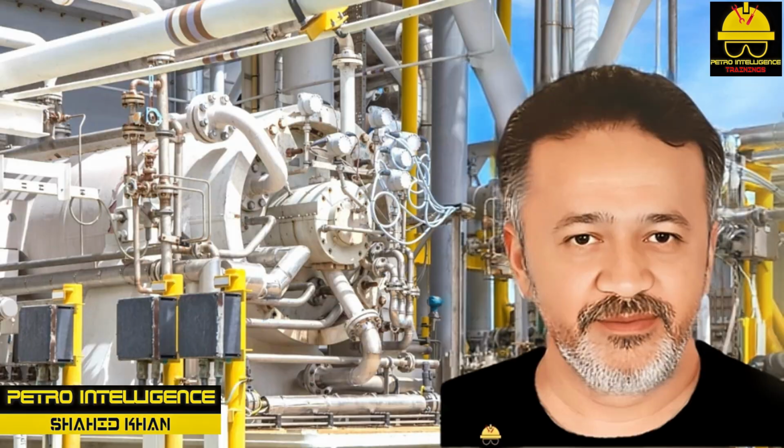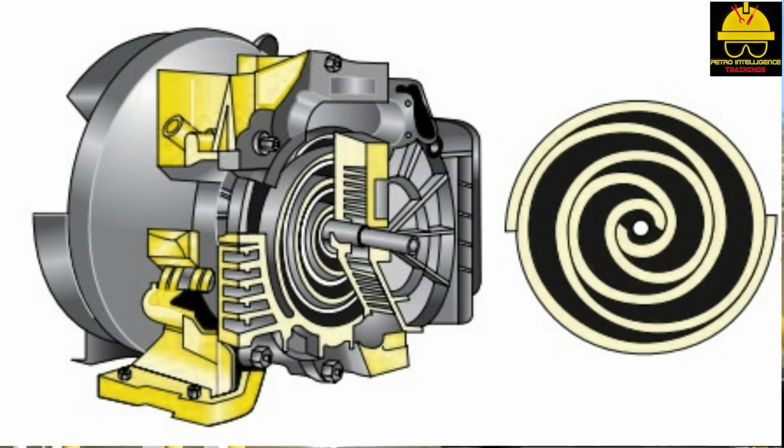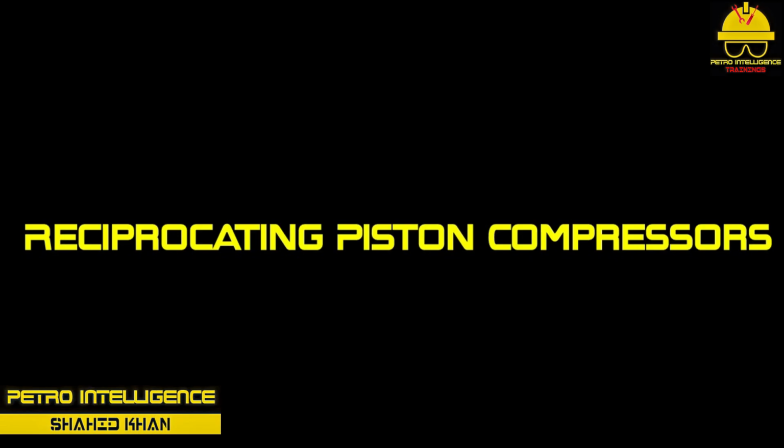Scroll compressors. A scroll compressor as shown in picture has two interleaved spiral vanes designed to compress fluids into ever-decreasing volumes. Scroll compressors run quietly and smoothly at lower volumes, trapping fluid between the scrolls. In most cases, one scroll is fixed and one orbits eccentrically without rotating.